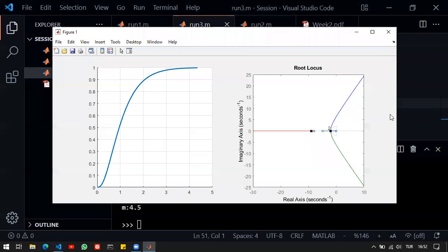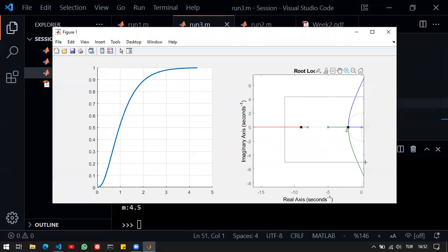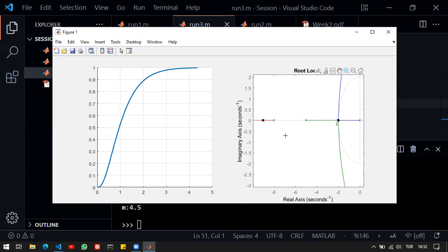Now, as expected, we are on the real axis here. And you can see, since the root locus is underneath the poles here, that one of the poles at -5 and the other one at the origin did approach this point and they met here. And then we have also a third pole here. So 2 on -2 and then 1 here somewhere. And you can also see that there's no overshoot. This looks like a response of a first order transfer function.